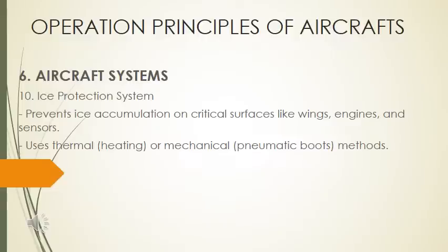Heating methods can be put in such strategic places where ice is likely to form, and also the use of mechanical pneumatic methods such as bleed air to blow away ice that forms. So, use of thermal heating or mechanical pneumatic boots to prevent ice formation.